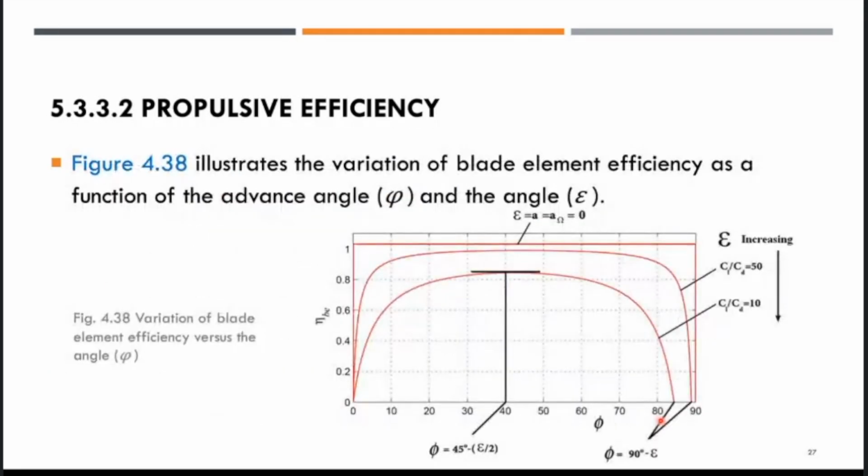All right. And figure 4.38 over here illustrates the variation of blade element efficiency as a function of the advance angle and the angle eta just now.